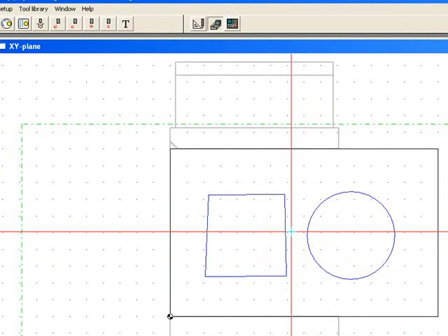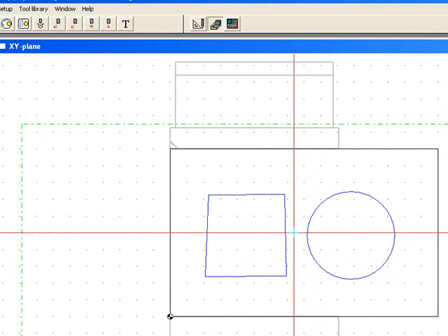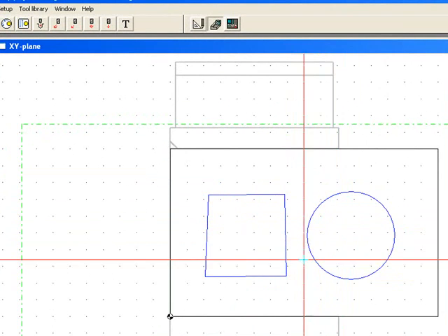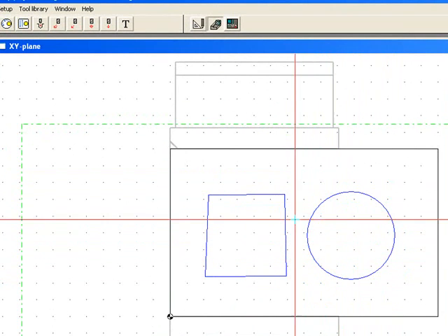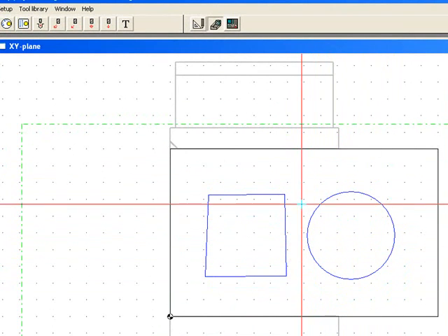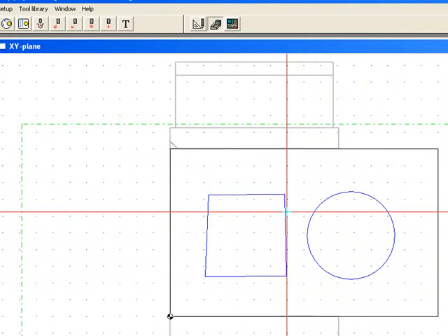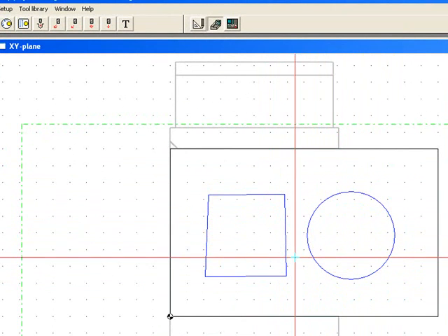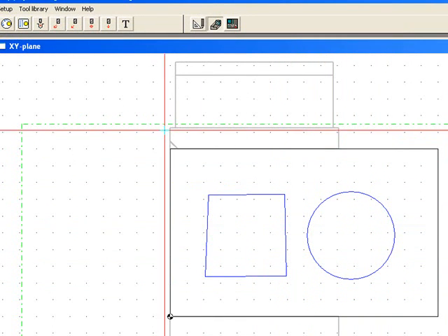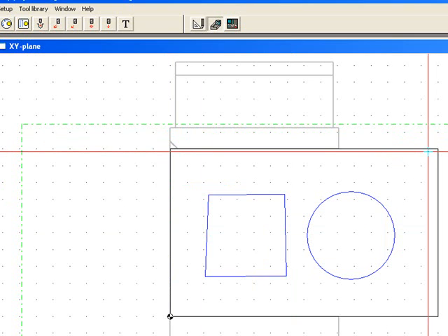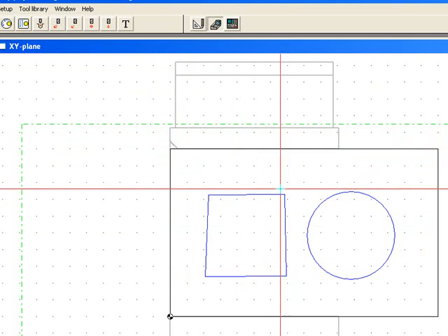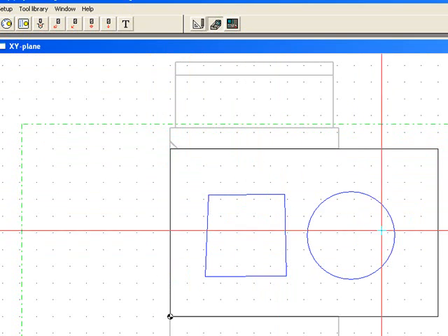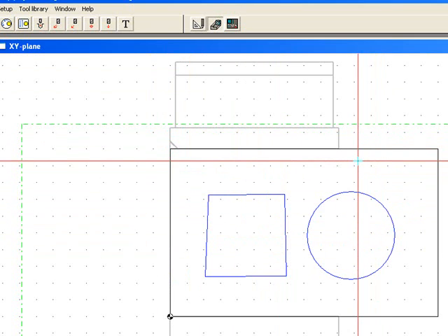Let's say these were a lot closer together. If they were less than 1/8 of an inch, I physically couldn't get the end mill through that area, so that wouldn't work at all. I'd have to separate these two with a wider space. So I'm going to show you how to pocket mill with islands. In essence, we're going to treat these as islands, so they're going to actually be sticking up out of the piece.